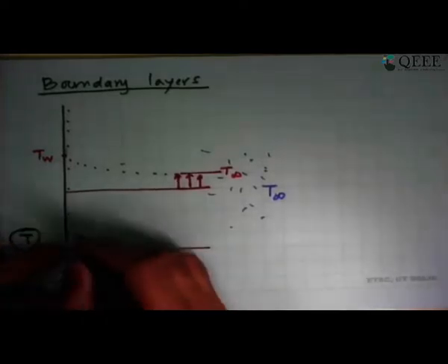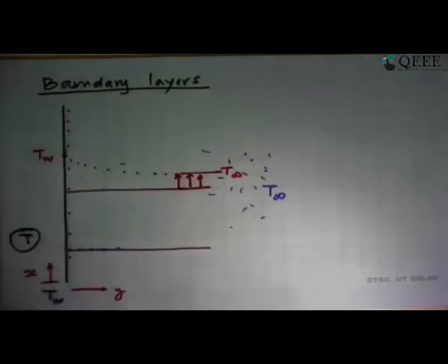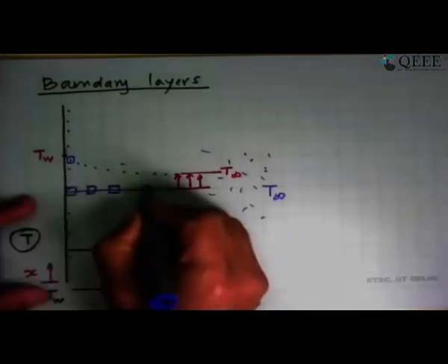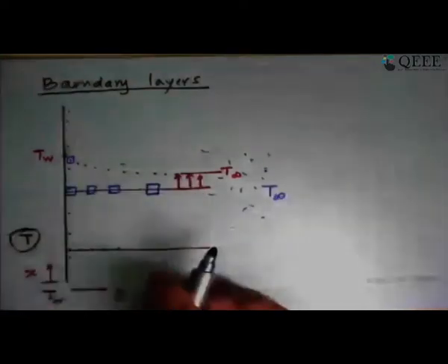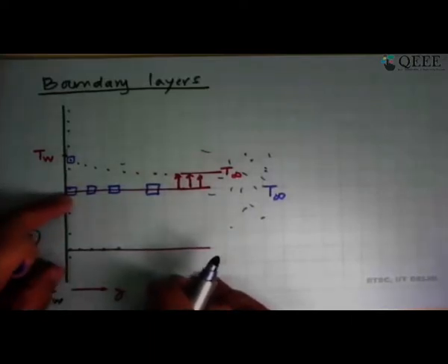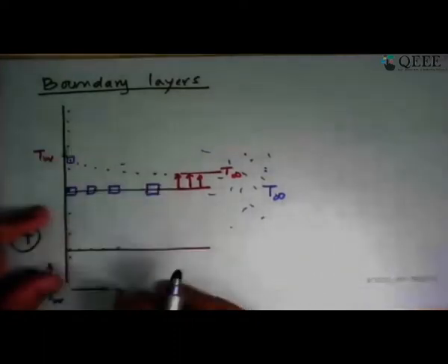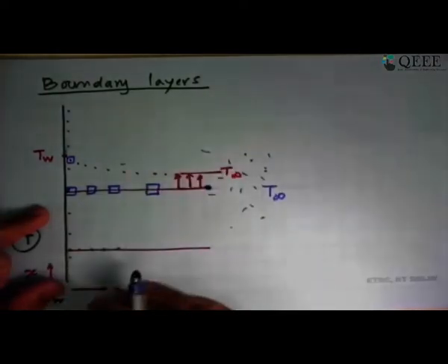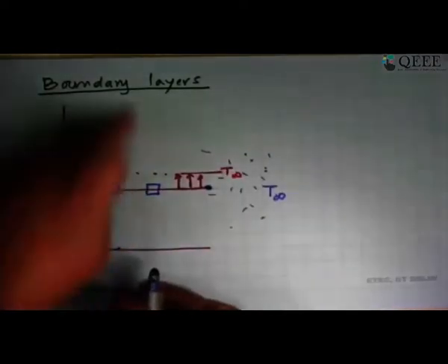And if we do that at another location, say over here closer to the bottom edge, what did this temperature gradient do? It starts with this fluid element here. The first thing that will happen is, where there is a temperature gradient, it will induce a velocity. So this element which is in contact with the wall will have zero velocity. And we know that far away, this element also has zero velocity. But in between, the fluid is moving.